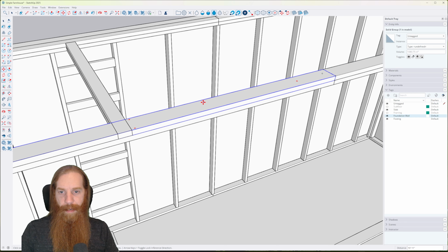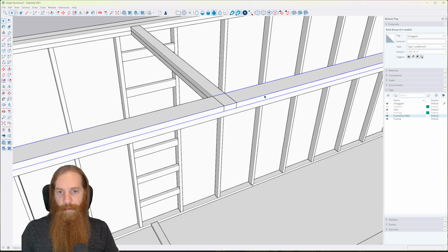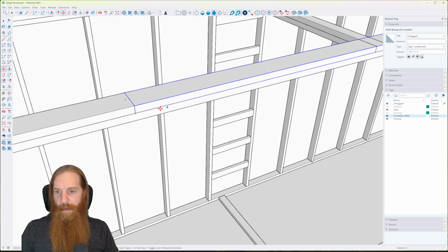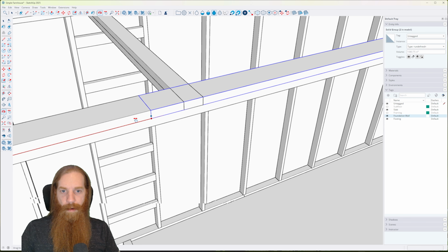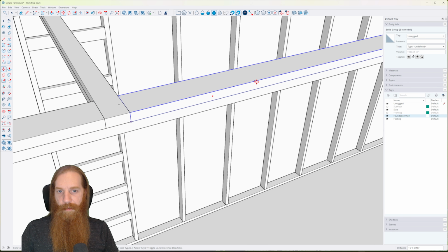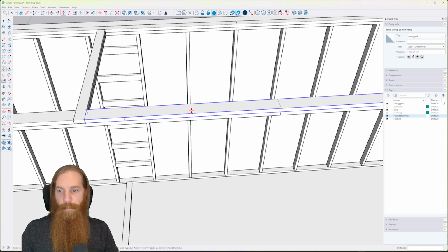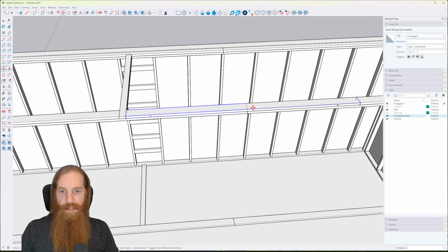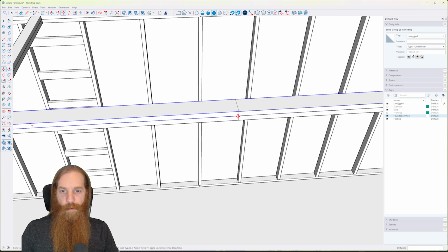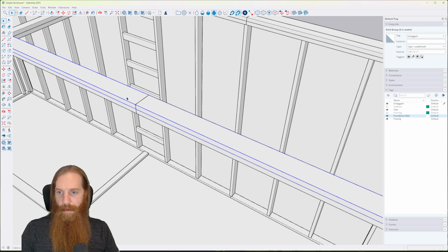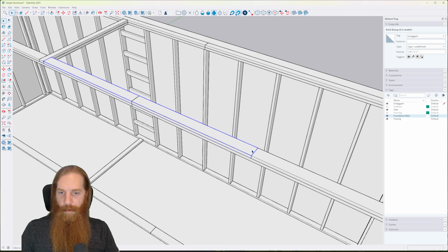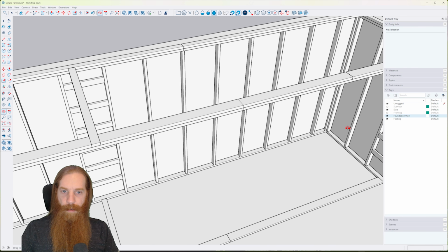But then, actually what I wanted to do, hold on, let's select that. We want to move it down to here like this, and you want your seams to be offset 4 feet minimum. So you can see we'll have a double seam right there. I don't want that. So what I'm going to do is go ahead and extend. This one already is, so what I actually am going to do is take this one.